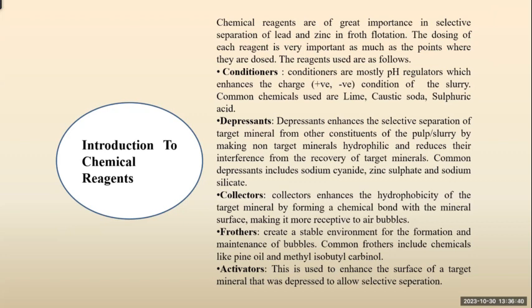So you have your collectors. Your collectors, in chemistry, we call them your ligands. They help you pick up those metals from the system. And you have the floaters. Examples of floaters are things like lime, fine limes, and MIBC. The common one is MIBC. They help to stabilize the froths, all those bubbles that will form, so they will not be cracking and falling inside the cell, because those bubbles are the ones carrying the metals.